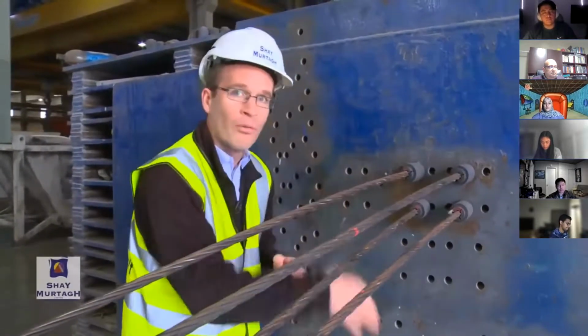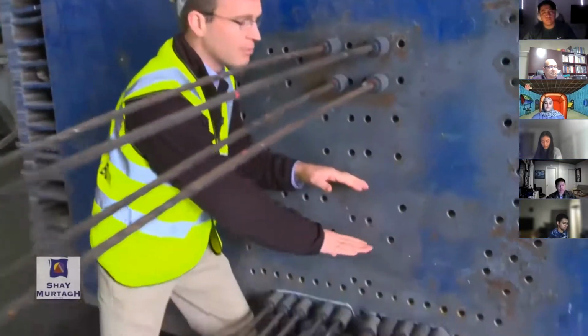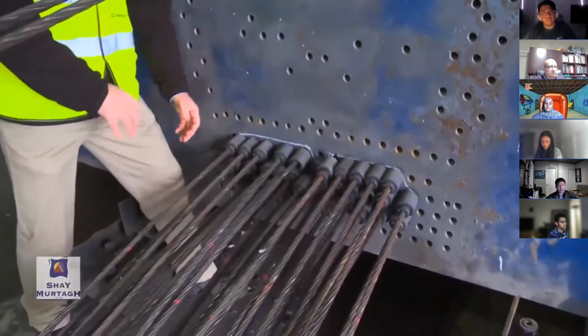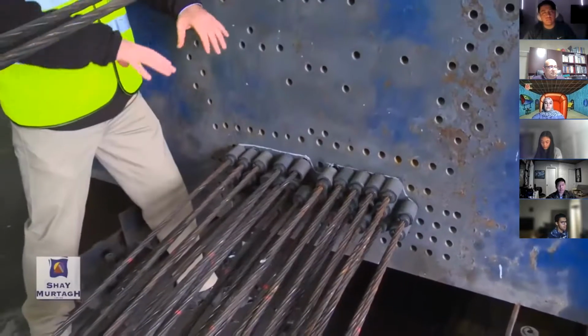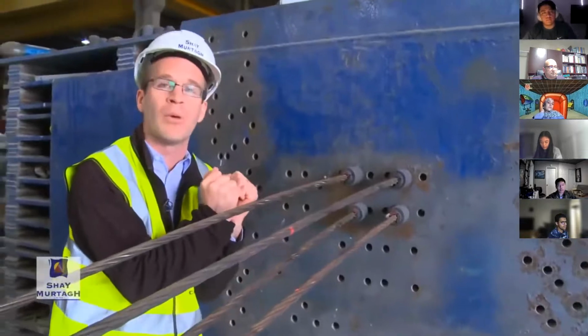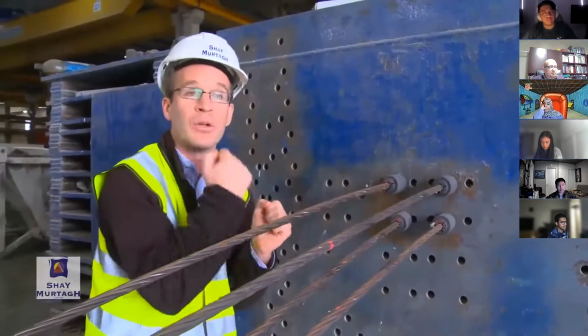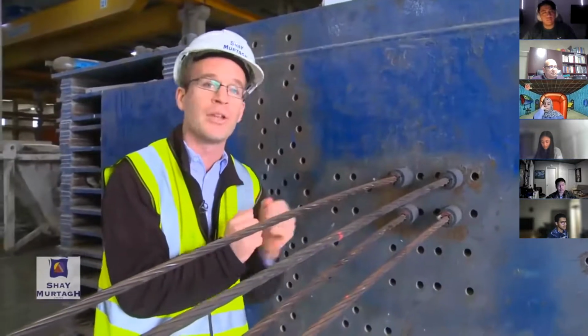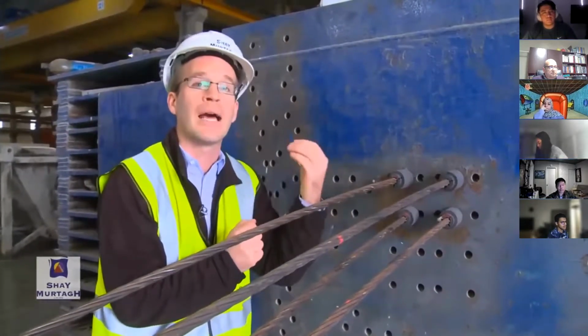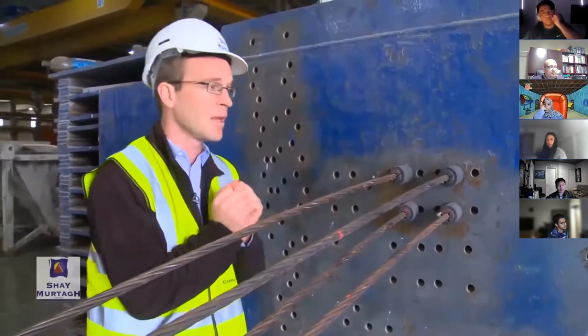Because the overall position of the strand is eccentric, removed from the centroid of the beam, that enables the application of pre-stress to also apply a bending moment that will counteract, and relieve, the bending moment that results from the applied loads, the loads that will be applied to the beam under working conditions.